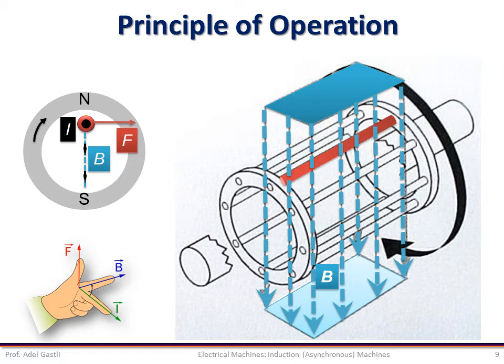For instance, at standstill, when the rotor is not rotating, this frequency of cutting the rods is the same as the supply frequency. Now, we know that according to Faraday's law, the changing magnetic flux seen from the rods of each pole induces a back EMF and hence a current in the rotor rod because the rotor circuit is closed.